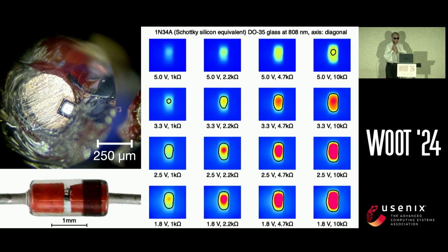As the system voltage decreases from TTL to CMOS to low voltage CMOS to 1.8 volt LV CMOS, and as the value of the pull-up resistor on the bus, which determines the speed of the bus, changes, we can force the value. By the time we get down to the bottom row, we can force the value of a bit against any reasonable value of pull-up resistor.